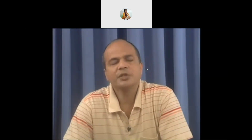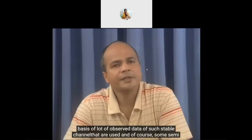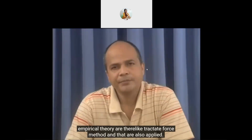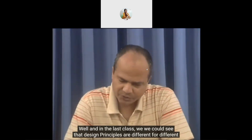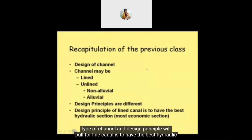Means the equation derived on the basis of a lot of observed data of such stable channels that are used. And of course, some semi-empirical theories are there, like the tractive force method, and those are also applied. Well, in the last class, we could see that design principles are different for different types of channel, and the design principle for lined canal is to have the best hydraulic section, and we started with the design of a rectangular channel, and then we could complete up to trapezoidal channel.